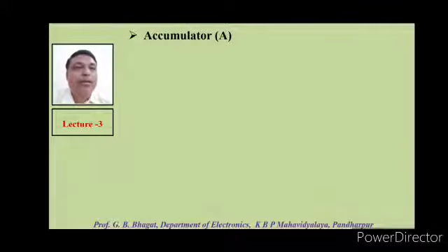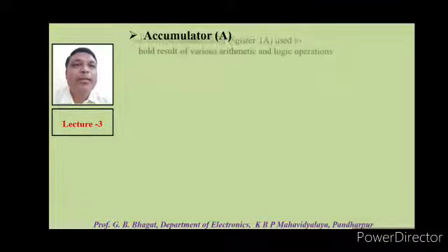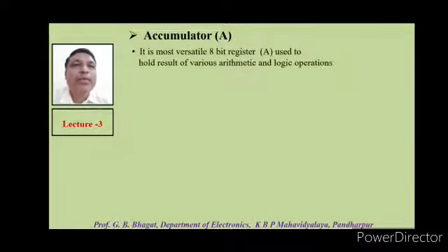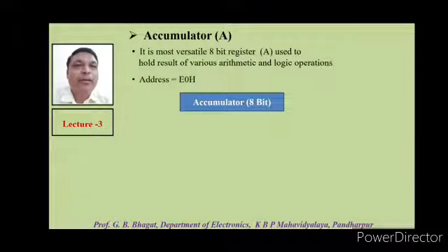The next SFR is the accumulator. The accumulator is one of the most versatile 8-bit registers, used to hold the result of various arithmetic as well as logic operations. The address of the accumulator is E0H. This accumulator has a size of 8 bits.